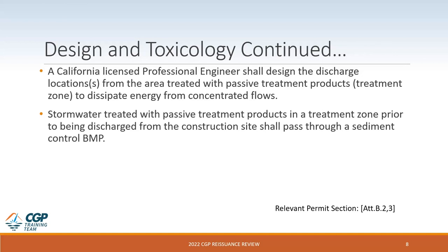Also, it's important that any stormwater treated with these products in a treatment zone before it's discharged from the site shall pass through a sediment control BMP, such as a sedimentation basin, as I showed on my second slide. And again, there, the goal is to really provide an opportunity for sediment to settle out of the stormwater. And also, if there is any unbound chemical, provide an opportunity for that to settle out as well and not leave the discharge or not leave the construction site.